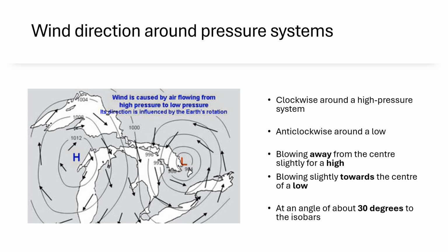To understand the likely wind direction from a synoptic chart, it is important to appreciate the way that winds flow around the pressure systems and the fact that on the surface they flow into a low pressure slightly and out of a high pressure system very slightly. From an aviation perspective, you should also be aware that the wind will veer as you ascend by several degrees. This means that if it is due westerly at launch, it will have a slightly northerly component at cloud base.